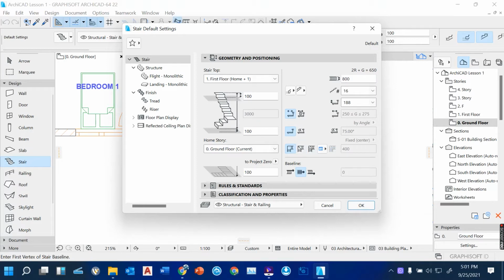So for our stairs, bottom of story, we can start it at 0, for example. You can do 0, 0. Yeah, so it goes up to 31. Also this one, you can put 0, so that it flushes with the top floor. Remember, our top floor is 3 meters, so we are starting from ground floor to second floor. So after setting all these, you just click OK.